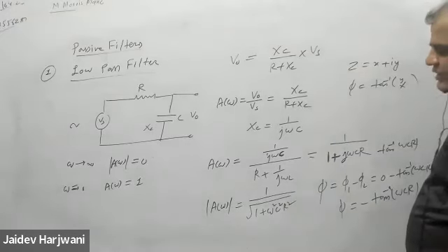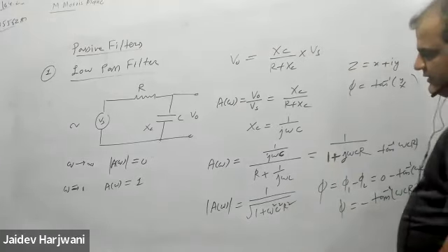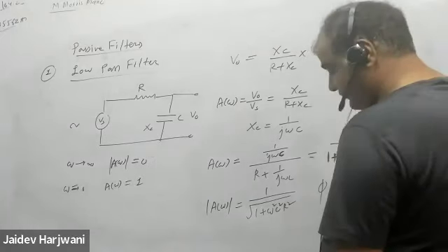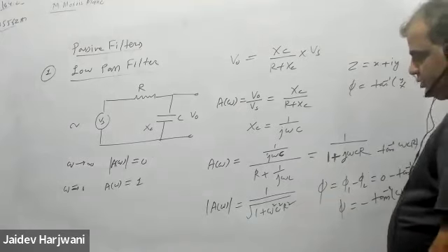So for low frequency, you are getting the gain. For high frequency, you are getting no gain. Basically, it is behaving like a low pass filter.